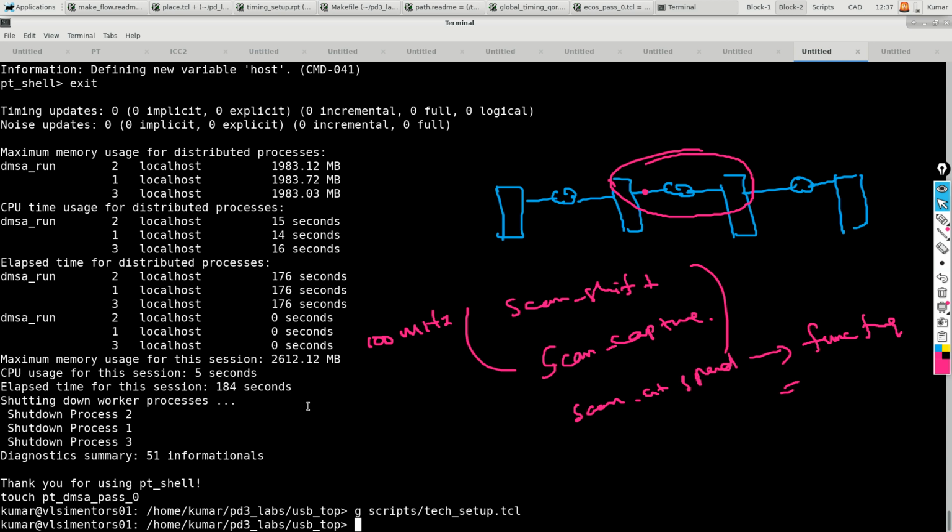If I directly give the command without giving the names of the ports which I have placed? No, the way I suggest is you should get the pins, or the ports, that are not on track. You should get that by running check pin placement or verify something. There are certain commands depending on the tool, and then you take that and you try. Only move those. I don't want you to move them globally, because you are in the placement stage.